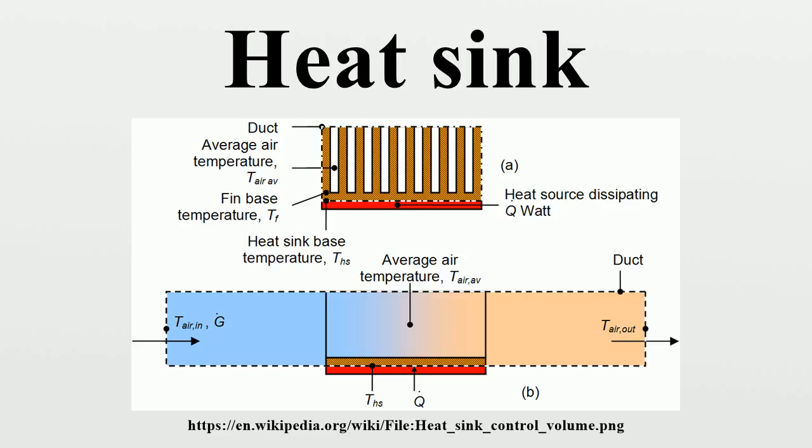Thermal resistance is defined as temperature rise per unit of power, analogous to electrical resistance, and is expressed in units of degrees Celsius per watt. If the device dissipation in watts is known, and the total thermal resistance is calculated, the temperature rise of the die over the ambient air can be calculated. The idea of thermal resistance of a semiconductor heatsink is an approximation. It does not take into account non-uniform distribution of heat over a device or heatsink.